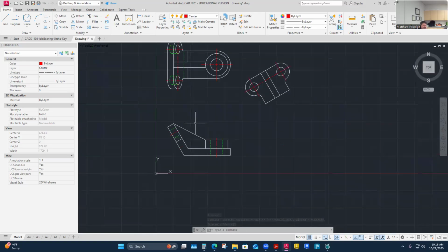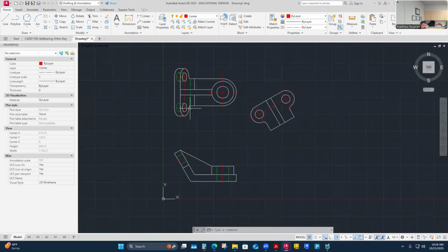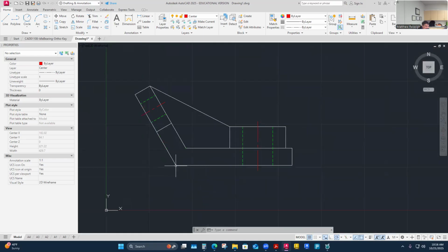So before I go to dimension it, I'm going to end this video where I just talk about maybe the datum and the controls of this thing. What are the best surfaces to base from? Well, definitely the base here. I feel like my front view datum is probably going to be this flat surface that's sitting down, and I'm probably going to pull some dimensions linearly up from this. Maybe I'm going to try not to chain them, but probably base quite a few of the dimensions in the height category from here.